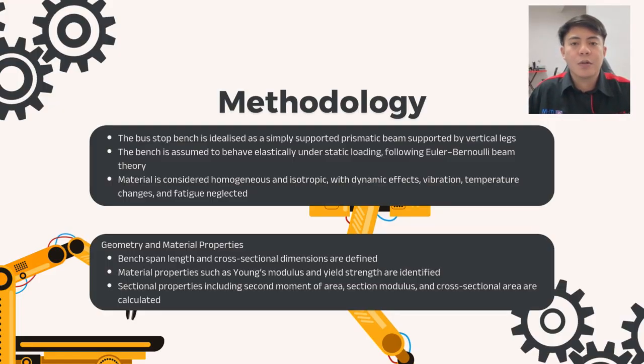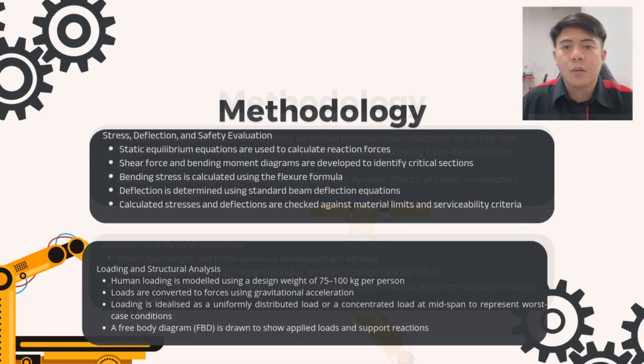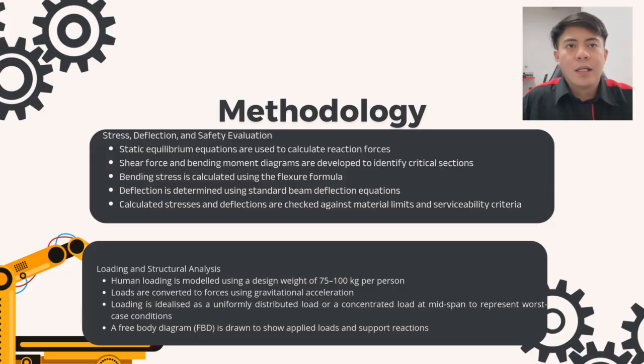Sectional properties including second moment of area, section modulus, and cross-section area are calculated. For stress, deflection and safety evaluation, static equilibrium equations are used to calculate reaction forces.